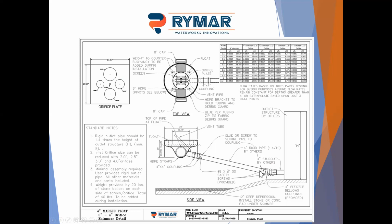One of the most common questions we get asked is the length of this pipe. We recommend it to be a minimum of 1.4 times the height of the outlet structure. So whatever that outlet structure height is, or if you don't have an outlet structure, the dam height, and that allows the skimmer to flex enough so that water doesn't come in over the top and it can get up to the top of the water. We typically like to say a minimum of 8 feet. If you had a pond that needed to go a little shallower or shorter, you could. We don't like to go excessively long because this pipe creates a lot of buoyancy and tends to lift the skimmer up a little bit, which has been some of our issues in the past, which we've now dealt with.